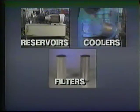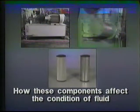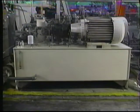In this lesson, we are going to focus on three components of a hydraulic system: reservoirs, coolers, and filters. We are going to examine how each of these components affect the condition of hydraulic fluid. We are also going to discuss some common sources of fluid contamination and what needs to be done to eliminate them. Let's begin with the reservoir. Often it's called the sump or tank. Basically, all reservoirs work the same way.